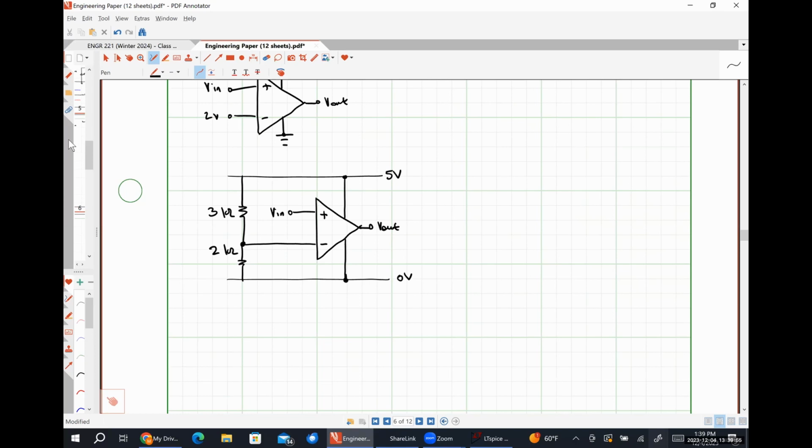We do have to draw the practical circuit. You could probably figure it out without it, but it will make a lot more sense. Actually, you should make an effort drawing it. We never use the ideal? Well, we're going to learn when and why we can use it first. One of the main conditions is negative feedback. If we don't have negative feedback, we cannot use it.